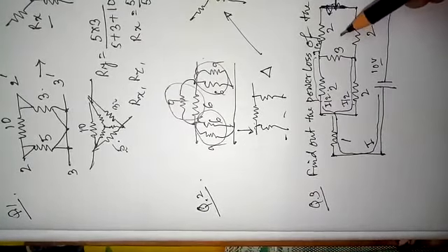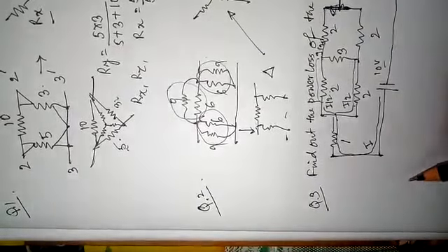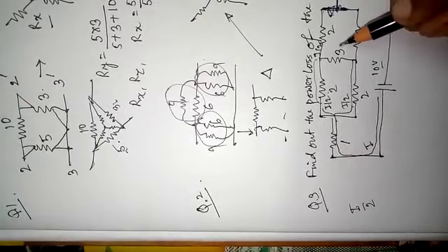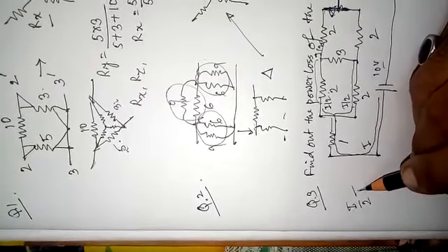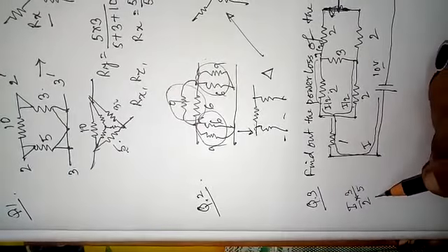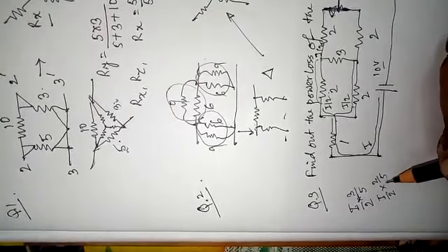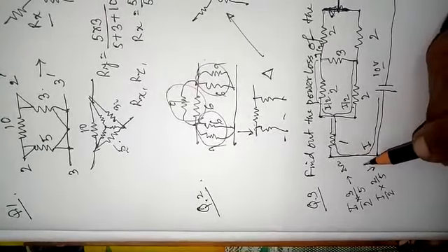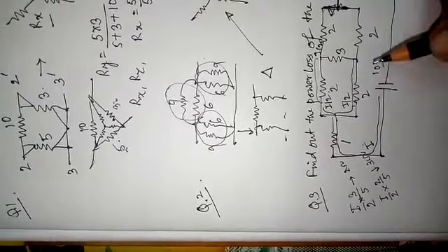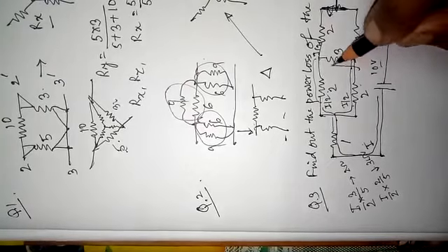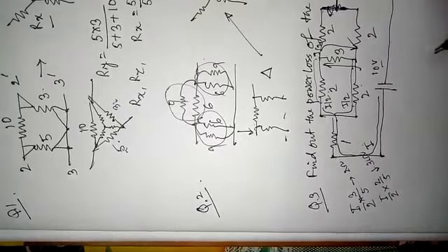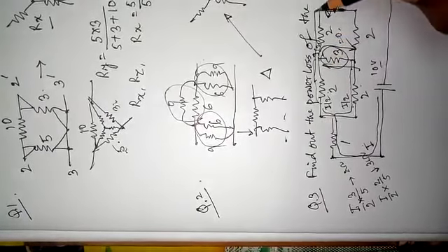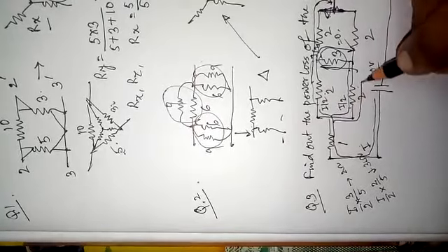If it is I by 2, the total is 5 and 3. So this part, another part is I by 2 into 2 by 5. Which one is the larger current? This will flow to that 2 ohm resistance and this will flow to that 3 ohm resistance. Now for this I by 2, one current starts flowing this way, and for this I by 2, one current starts flowing that way. So finally the net current in this branch is equal to 0. The current is not coming to this part, it's simply coming to this and joining this terminal, and this is also coming and joining this terminal.